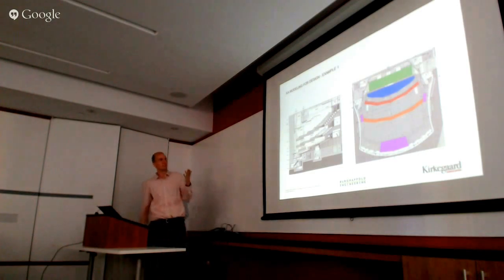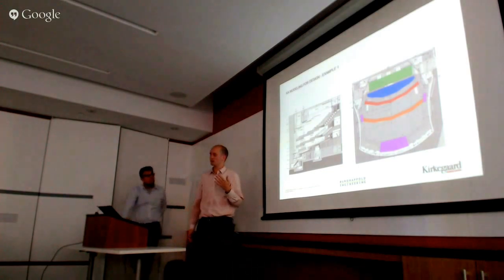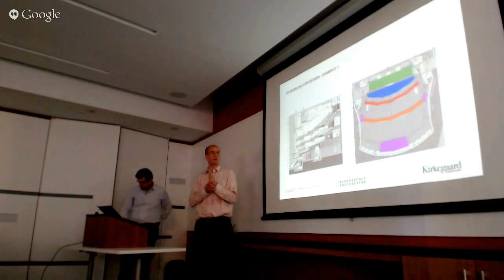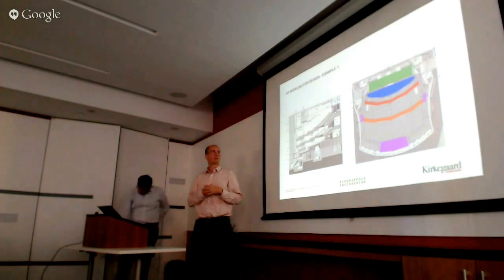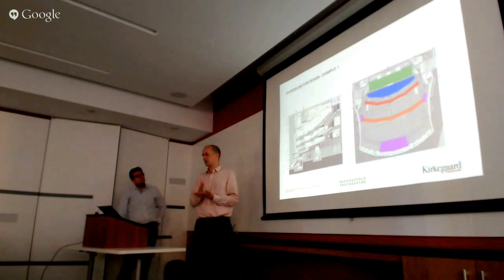Do you want to move over? Sure. So this first modeling example is more of a later-in-design issue. This is the University of Iowa Hancher Auditorium. It's a large multi-purpose auditorium, a large, tall space, and we needed the reflector elements in the house to provide overhead reflections for the entire audience area. That was going to be at an appropriate time window, and we weren't going to have areas that didn't get a reflection and areas that did, while still only having, as you can see, not that much area actually covered by those surfaces.